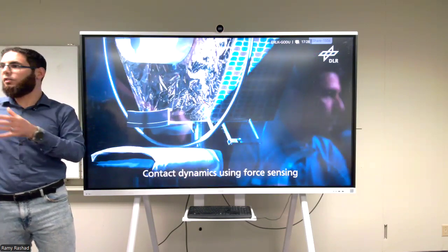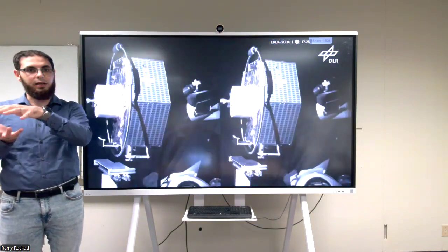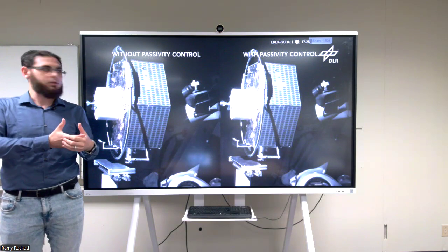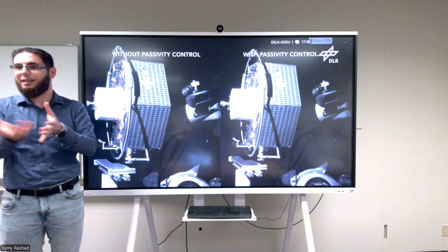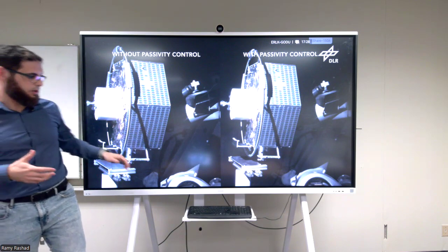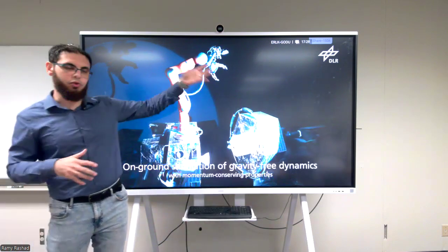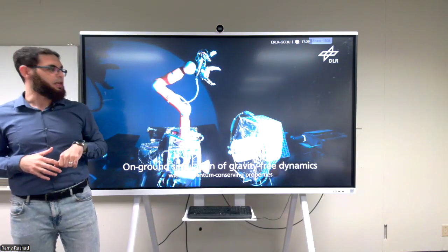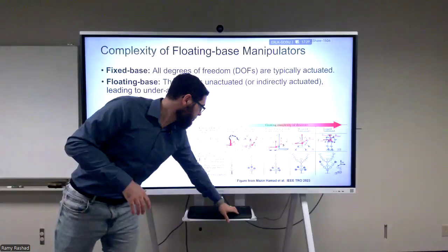And how does it do that? It does it by impedance control. So this is one robot on another robot. The other robot has impedance control so that it's simulating completely the absence of gravity. And now they're interested only in the top robot, trying to simulate something that it will be doing in space, for example, capturing this satellite or doing something there.